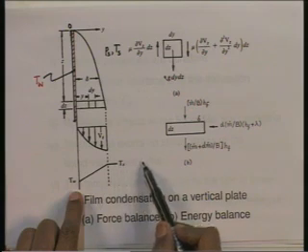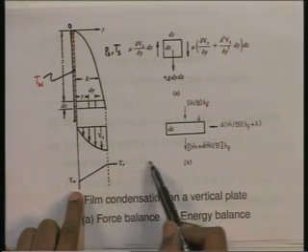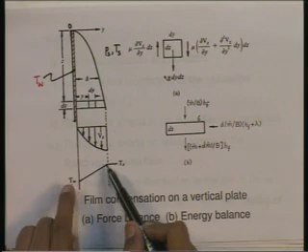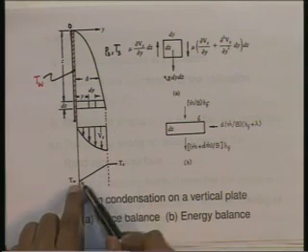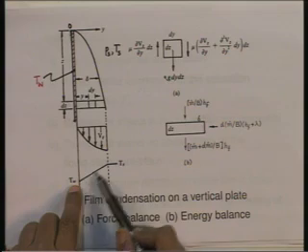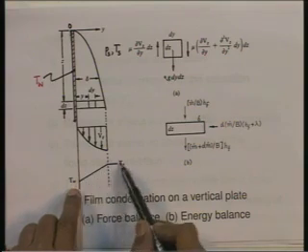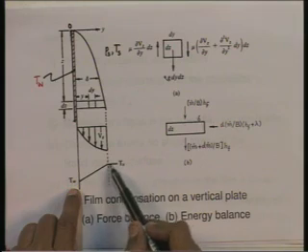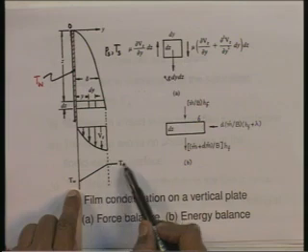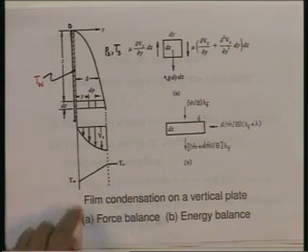In the vapor space, the temperature is going to be constant T s, and then at the wall it is T w. So, across the liquid film I am going to get a straight line like this. So, the temperature distribution in the liquid film and in the vapor space based on assumptions 2 and 5 will be as I am showing you just now. That is where we have used assumption 2 and assumption 5.